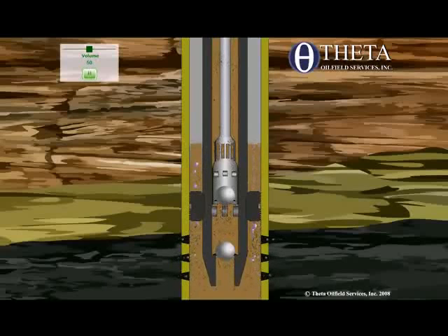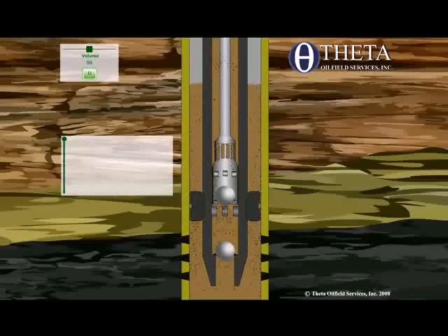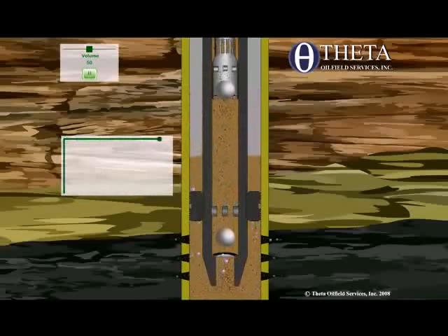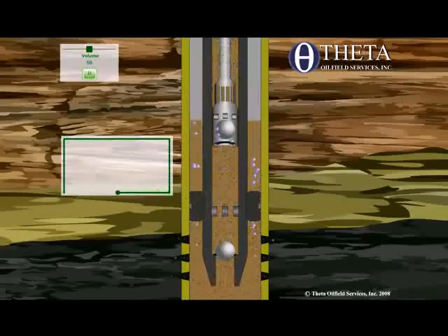And then when the downtime is over, whether it's 5 minutes, 10 minutes, whatever you set your controller for the downtime to be, it'll kick back on, and now you have enough fluid to keep the pump full. So now the pump starts back up. Now there is enough fluid to keep the pump full for a few strokes, and that cycle will repeat.